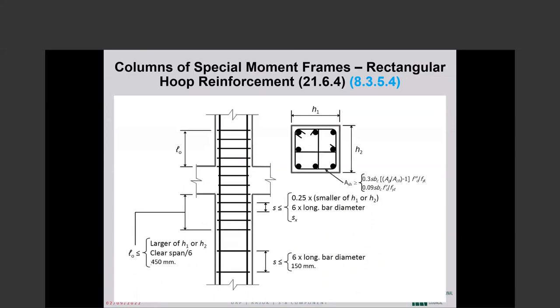Now, why is the 100 ksi limit for confinement reinforcement so important? To explain, I brought up the requirements for special reinforced concrete columns, which we will discuss later on in the presentation. When we detail a special reinforced concrete column, we consider a region of potential plastic hinging at each end, the length of which is specified in the code.